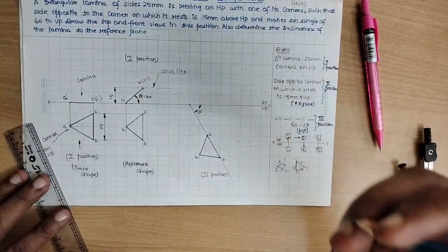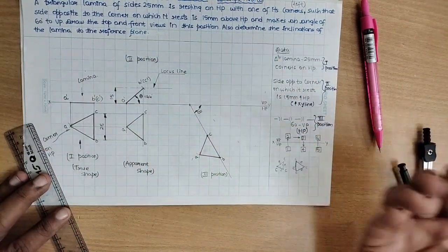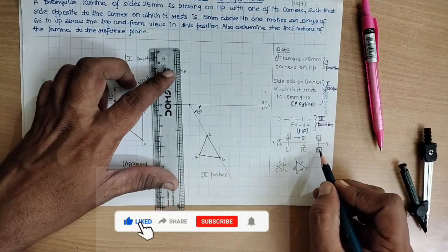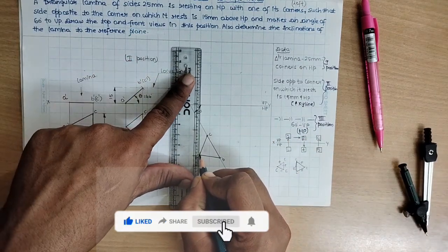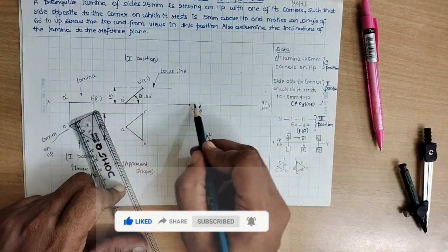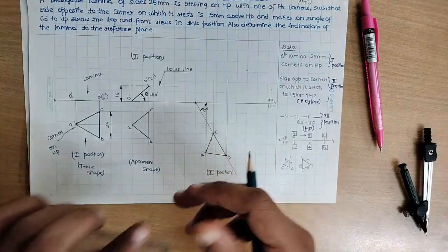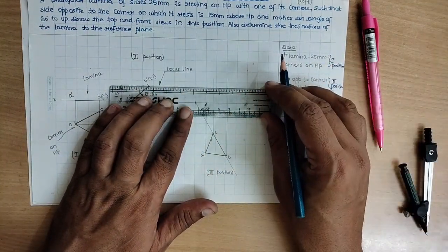Dear learners, just for your knowledge, the sketch we are doing is called the change of position method. From here to here we are changing one position, from here to here we are changing one more position. Now projection from the point A, let us go for the last position. From the point A, I will drop a perpendicular projection line till it touches the XY line. Now projection from the point B. Similarly, projection from the point C. Same thing, go with the horizontal projection, that is nothing but the extension of that 15 mm line.